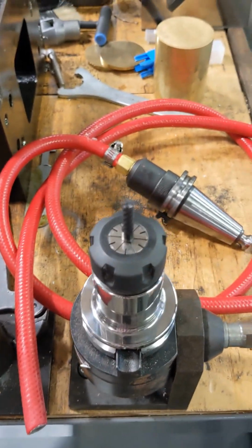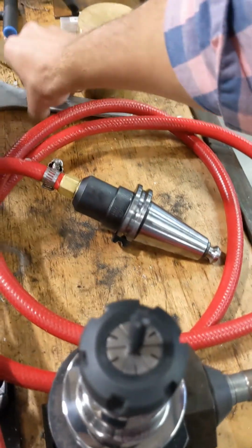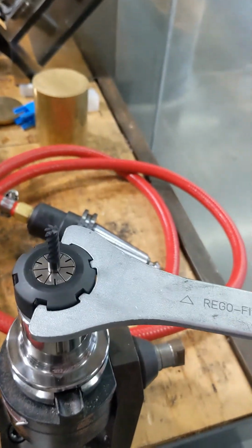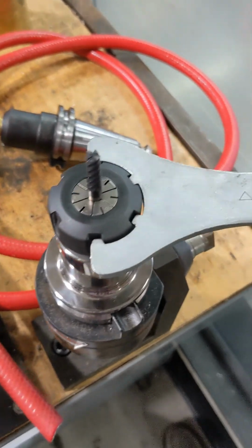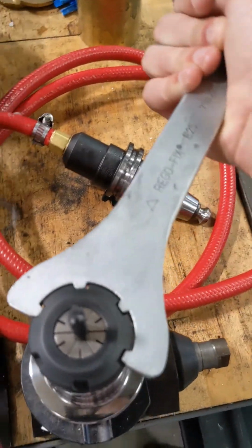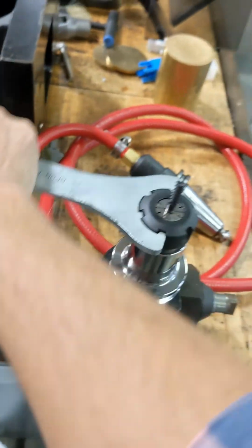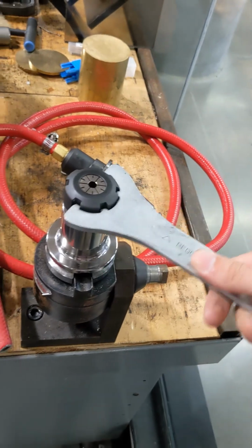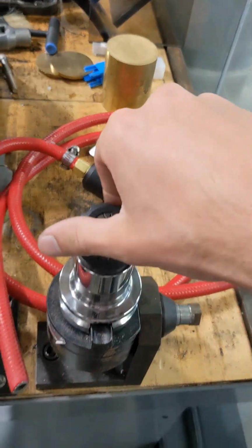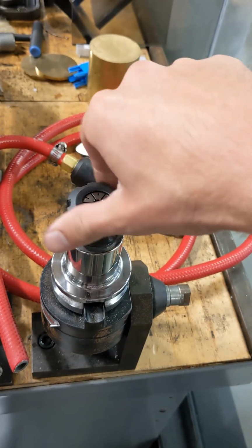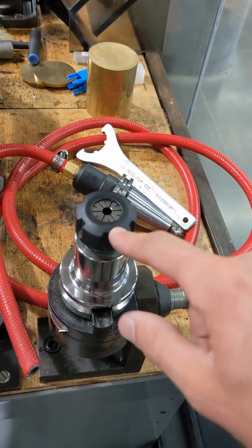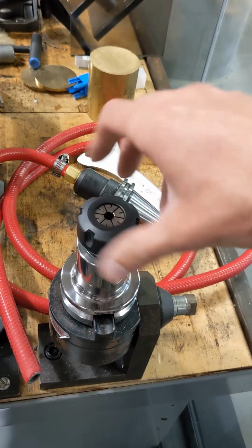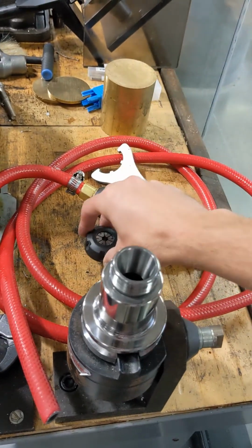This is our tool mounted on our tool holder. I need to remove the collet from this tool along with the end mill that's currently in there. So I'm going to take this wrench and lefty-loosey, righty-tighty. So I'll just loosen this. There will be one sort of hard stop in the holder that you'll find, and you just want to get past that. You don't want to do what I just did, which was let the tool drop in there. Usually you want to have one hand holding the tool. Because I'm filming, I did not do that.